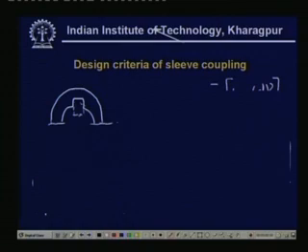Once the key is designed, then we have to check for the pressure or the stress inside the sleeve. What you see is that there the stresses will be developed. Here we have the pressure which is transmitted from the shaft to key to the sleeve, and that causes a tensile stress over here. So whenever such a situation occurs, there is a possibility that it may break from this point. Now we have to calculate the tensile stress.